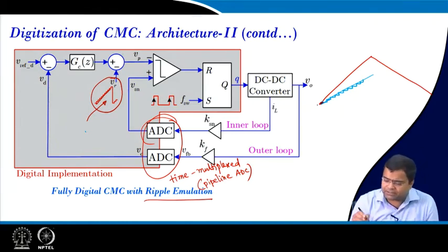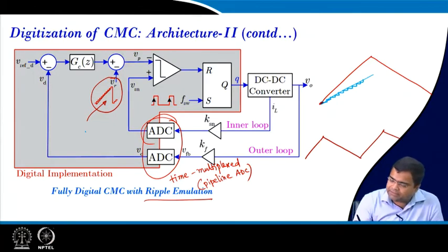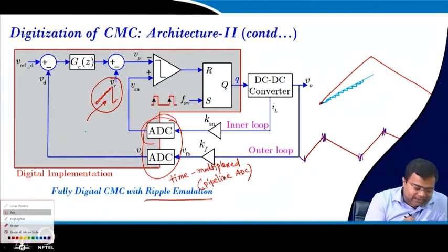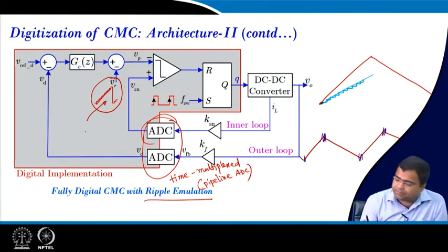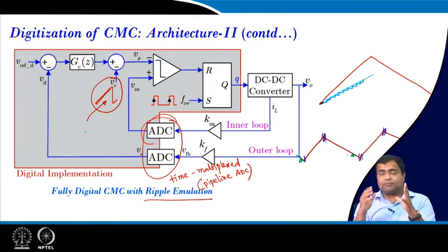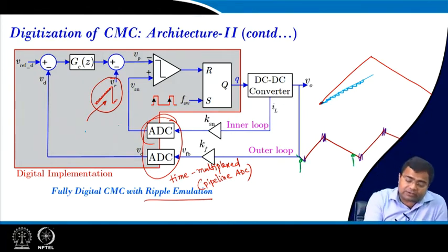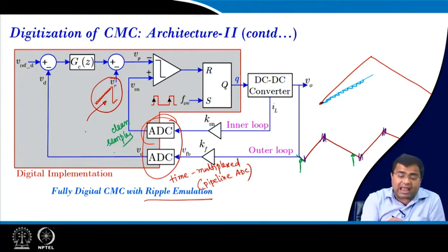Suppose I am talking about the inductor current like this. Now, when you go for sensing current, sometimes at high frequency, there can be some kind of spike here. For a very high frequency current sensor, there can be a spike. But if you take the current sample, for example, a clean current sample here before the switch turns off, these are my clean samples, then you can add a ramp.